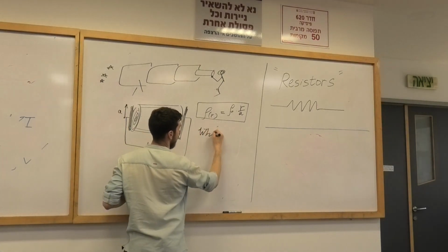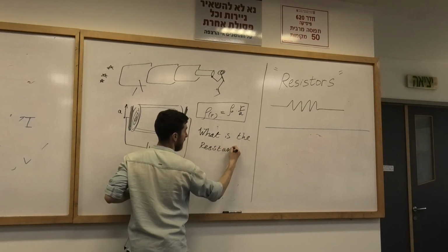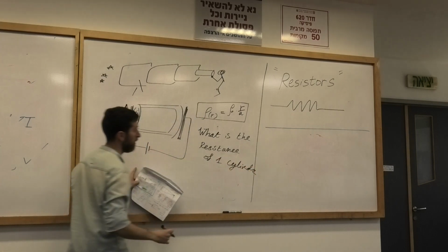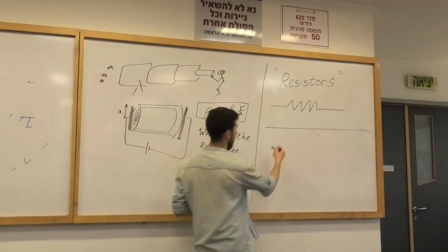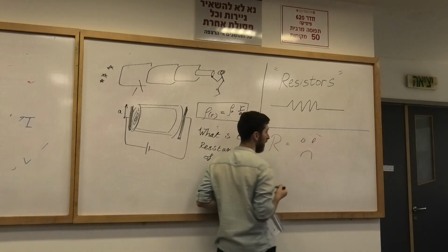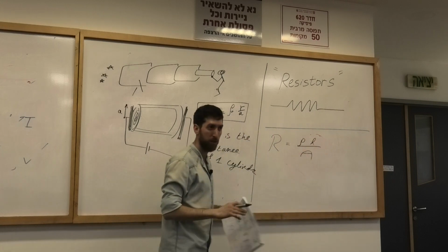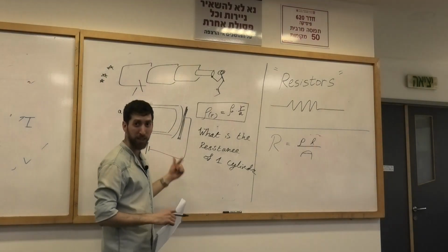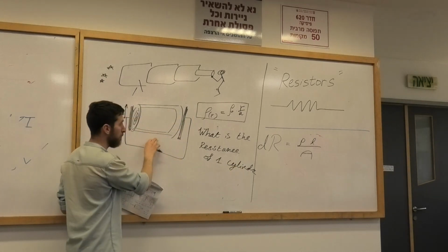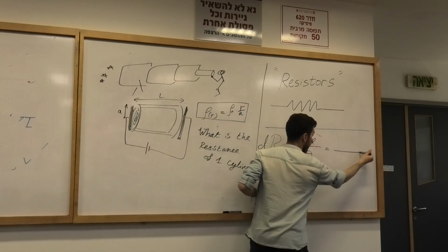Okay, what is the resistance of one cylinder? So what is the formula for resistance? Do you remember? R equals smiley face. That's how I remember it. Right, smiley face. Do this line here, A, rho, L, my method, and we're talking about just a small cylinder, one cylinder, so we're actually talking about dR, right? So right, we need to understand each component. These have a length of L, so what are the contributors that we have here?